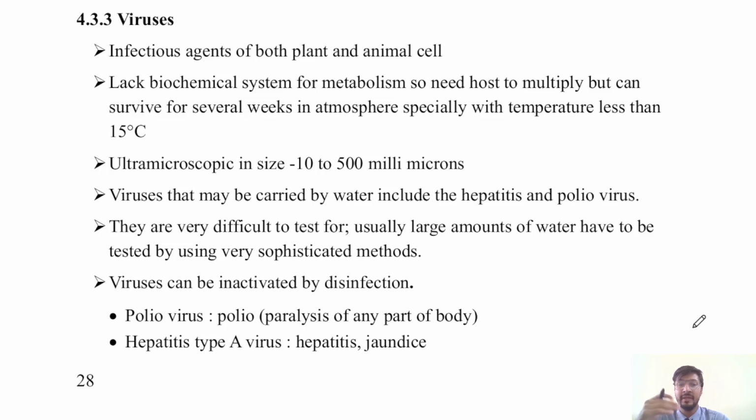Viruses that may be carried by water include the hepatitis virus and poliovirus. They are very difficult to test for. Usually a large amount of water has to be tested using very sophisticated methods. Viruses can be inactivated by disinfection.